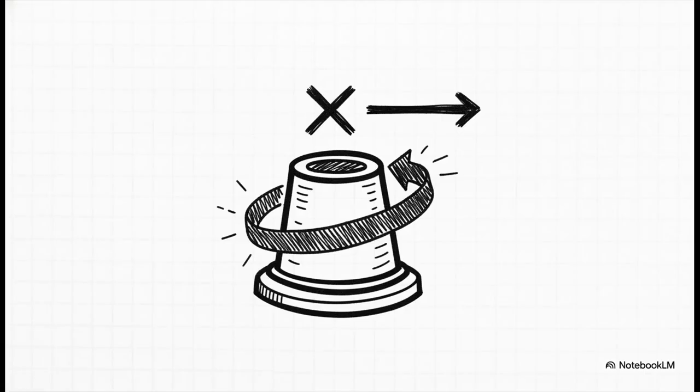Now let's make it move. The setup tells us the entire base is rotating around the vertical z-axis at an angular velocity of 5 radians per second. Because it's around the z-axis, we're going to write this as 5K. To find the linear velocity of joint B, which we'll call VB, we take the cross product of that angular rotation and our position vector. When we cross 5K with our RB vector, the math tells us joint B is moving at -3 meters per second along the x-axis, represented by the I vector.